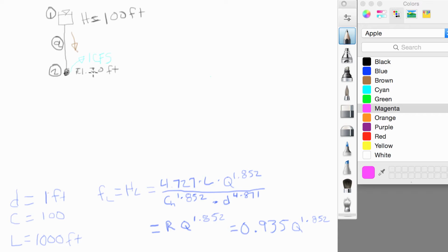So what we're going to do today is apply what we learned in the first video of EPANET hydraulics, where we showed how the Bernoulli energy equation can be written from one point in the system to another point in the system, and then we can describe the head loss or the energy loss between those 2 points given some flow in the system with one of at least 3 different head loss equations: Hazen-Williams, Chezy-Manning, or Darcy-Weisbach. We're going to choose Hazen-Williams for this video, but you can look up the other two, and that's also available in EPANET based models.